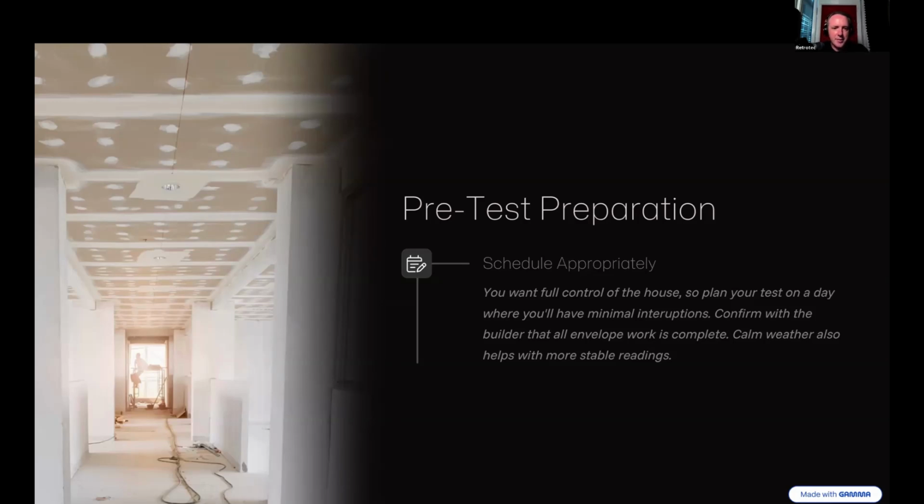And a lot of times, depending on how that home is constructed, you can show up pretty early. If you're a home builder listening, I highly recommend you look up some of Jake Bruton's content. He's a contributor to the Build Show. What he does is he actually tests his houses 3 times throughout the build. Right when that air barrier is finished, and a lot of times what they do is the air barrier will include the floor, the exterior walls, and then the roof deck. So you can go ahead and do a full blower door test without any insulation or drywall installed. And that's a really nice way to do it.